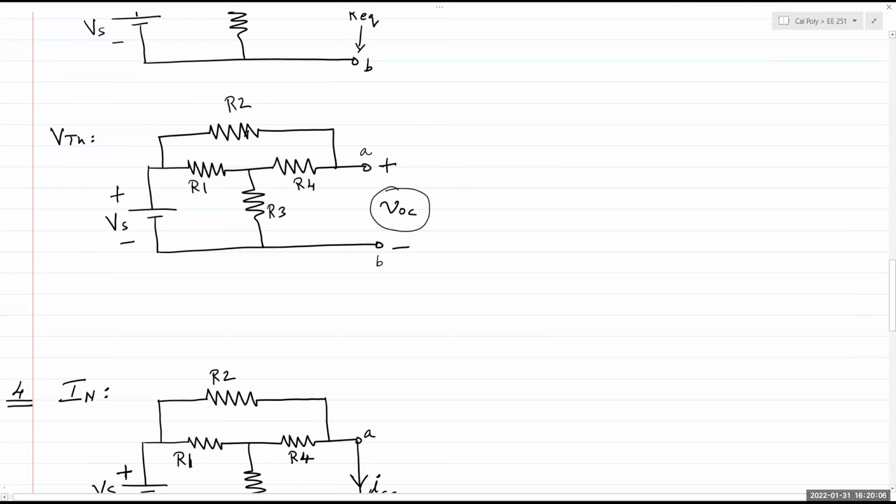Now for this circuit, you can choose node voltage analysis, mesh current analysis, or series parallel equivalent analysis, meaning you reduce the circuit to one single resistance and apply Ohm's law and find the voltage and currents that way. But I can see that there's one voltage source and only 3 nodes in the circuit. And so it makes sense to use node voltage analysis. If I use node voltage analysis,